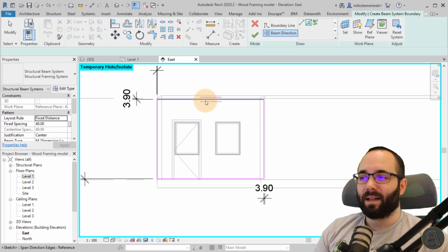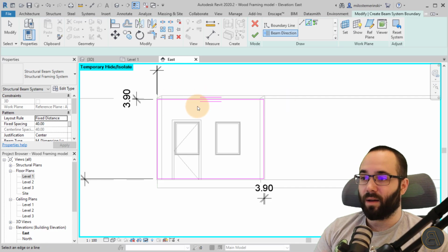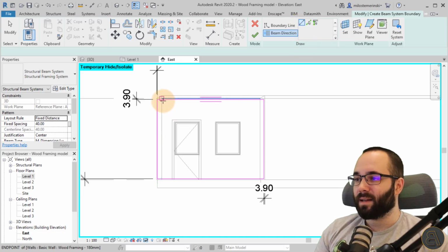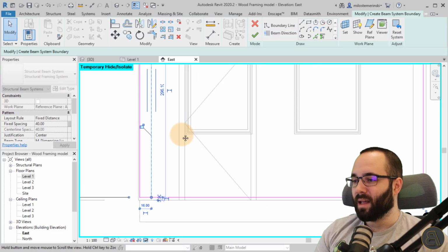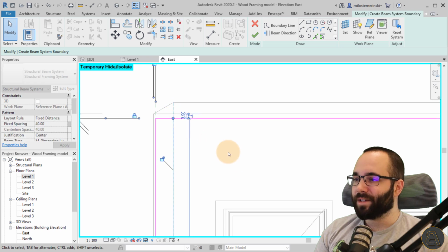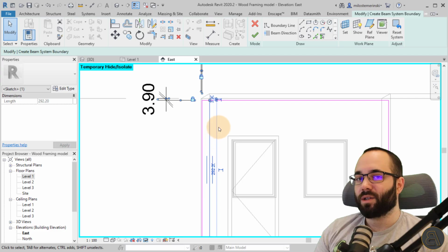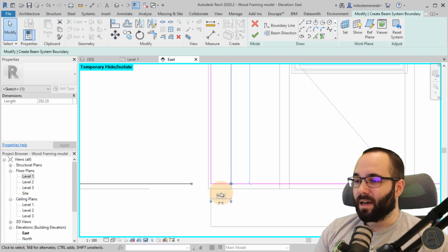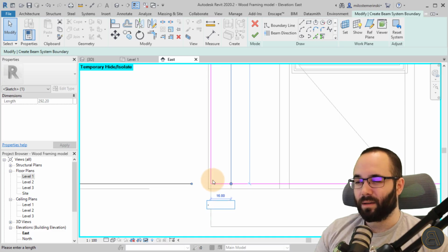That's basically indicating that the beam direction is this, horizontal. Now, we want it to be vertical. So what you want to do is use the line and create a vertical beam direction, obviously. But then also, I'm going to use that beam direction line to define where the position of the first stud is going to be located. So in this case, I want it to be from the edge point, that should be 0.195.